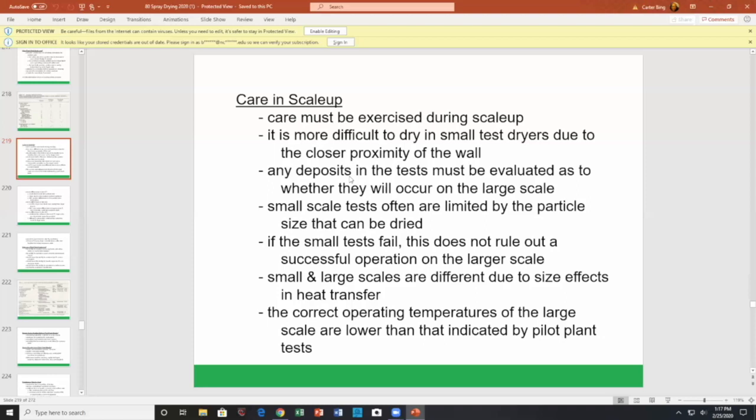Now, how do you figure that? It means that scale up is a tricky area, and lots of phenomena that happen on the large scale do not happen on the small scale, and vice versa. For example, this morning you may have gotten up and turned on the faucet in your kitchen or your bathroom. It's a 2-inch or an inch pipe, right? Flow rate comes out, no problem. You turn it on and off without paying much attention. You don't expect any water hammer or shock waves in your processing line.